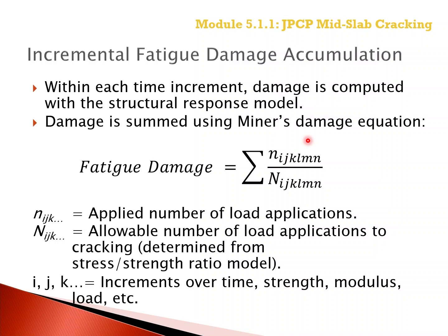So the fatigue damage accumulation is simple in concept, but there are many calculations of the actual number of load applications within a specific axle load, specific time period or climate, and location of the slab divided by the allowable number of load applications for that same specific condition.